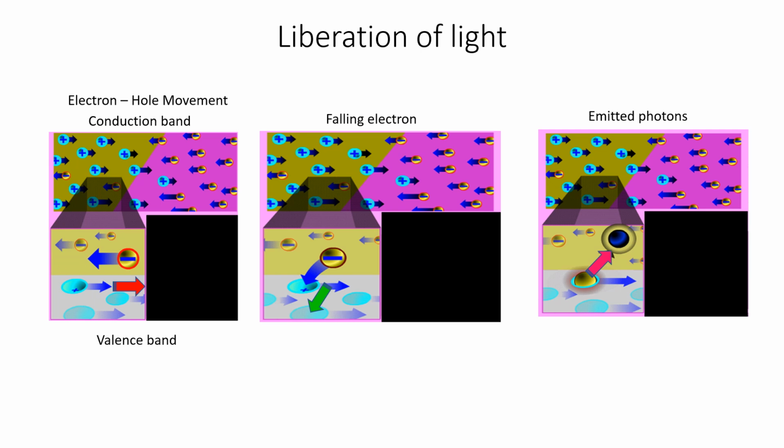As a result of recombination, the electrons lying in the conduction band of the N region, shown in the diagram, fall into the holes lying in the valence band of the P region, as shown in the diagram. The energy difference between the conduction band and the valence band is radiated in the form of light energy.